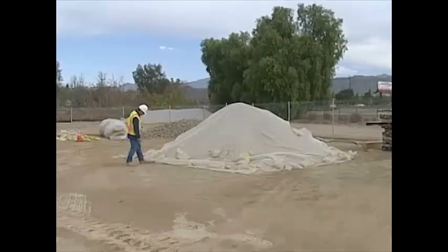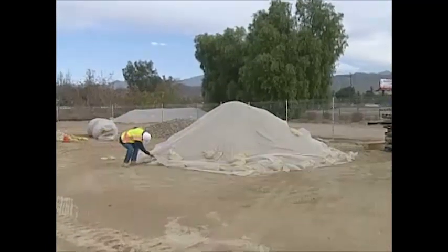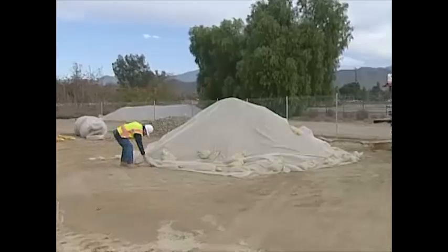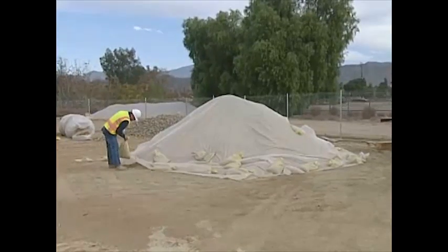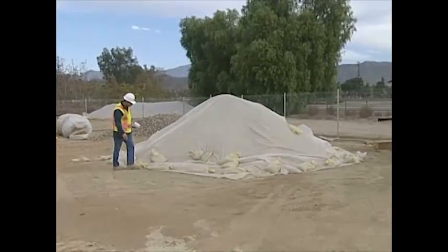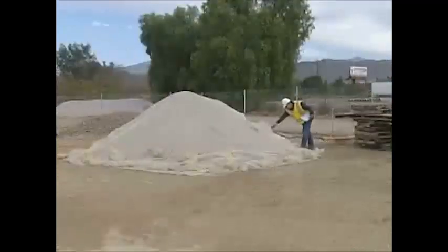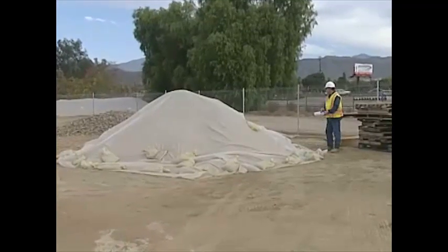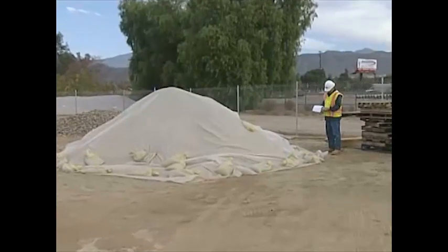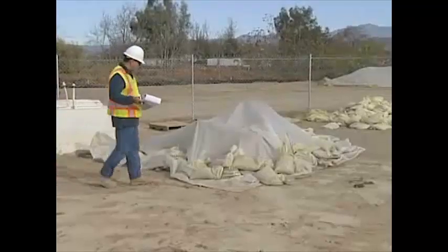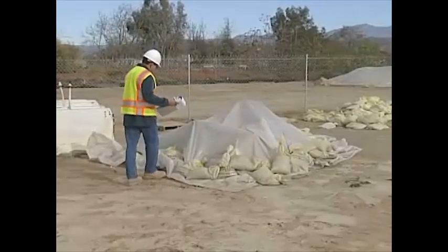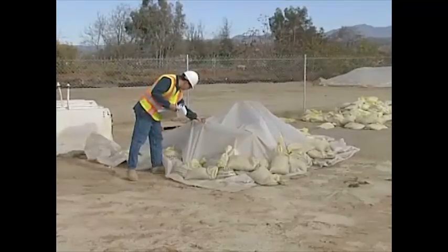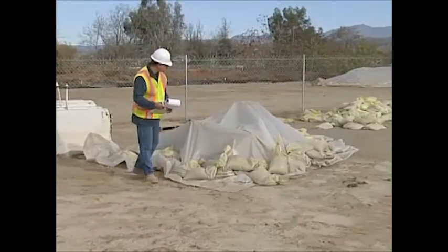For stockpiles of Portland cement concrete rubble, asphalt concrete rubble, aggregate base or aggregate subbase, during the rainy season, cover or protect non-active stockpiles with a temporary perimeter sediment barrier at all times. During the non-rainy season, cover or protect the non-active stockpiles with a temporary perimeter sediment barrier prior to the onset